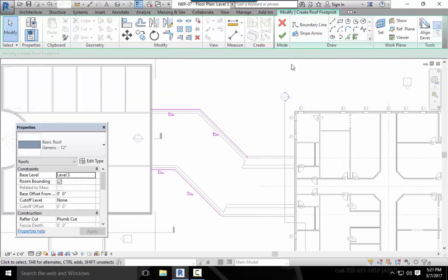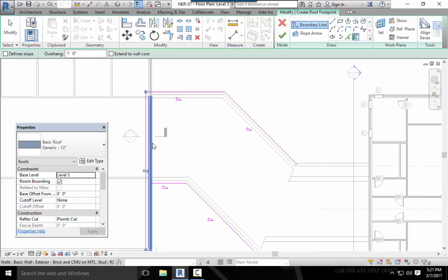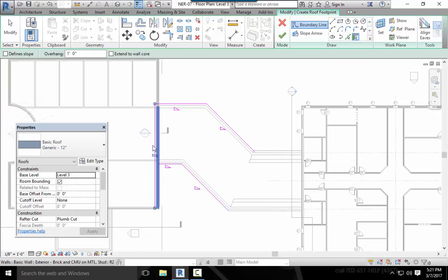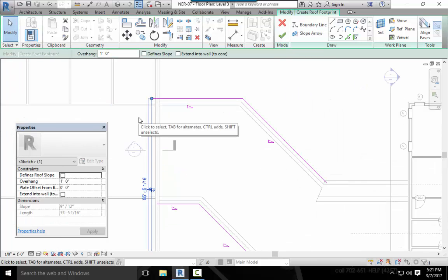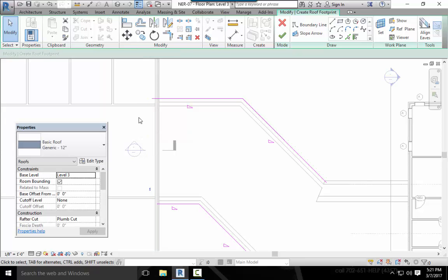Now I need a couple lines over here. So pick wall on this side. Oh, no, that's all sorts of ugly. It's at a 1 foot offset, so that didn't help me there. Let's just delete that line. Use trim quickly to trim these up.